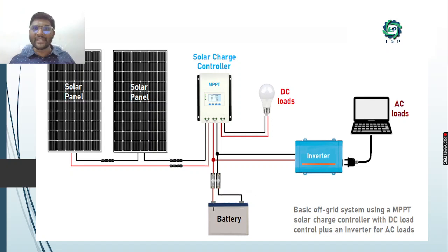When you go for an on-grid system, if you are using your power sources during the daytime, in normal sunshine days, then it is better to go for an on-grid system. But if you are using power only in the evening time or sleeping hours, at night time, then in such cases it is better to go with the off-grid system.